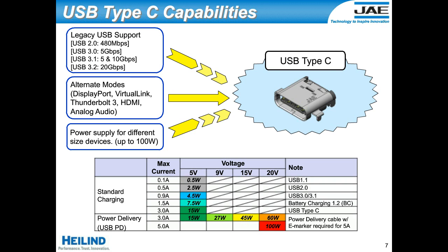Also, a brand new capability that the Type-C made possible was the capability to support what's being called alternate modes. So alternate modes actually allow the same USB Type-C connector to transmit other types of signals, either in addition to USB, so along with USB and other types of signals, or actually instead of USB. So instead of sending USB signals, it would be strictly whatever this alternate mode signaling was. Just some examples of what these alternate modes could potentially be.